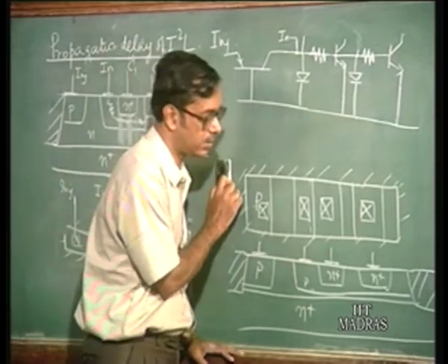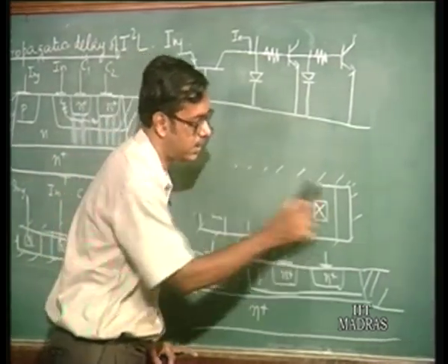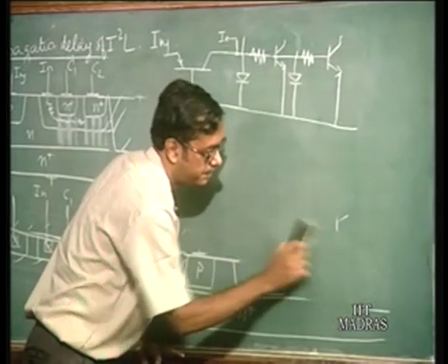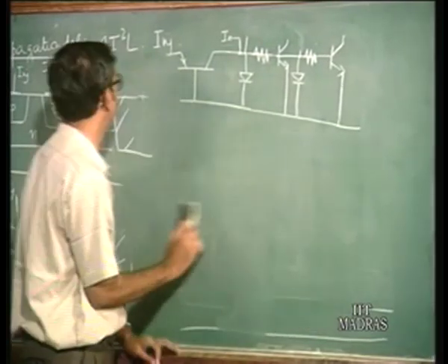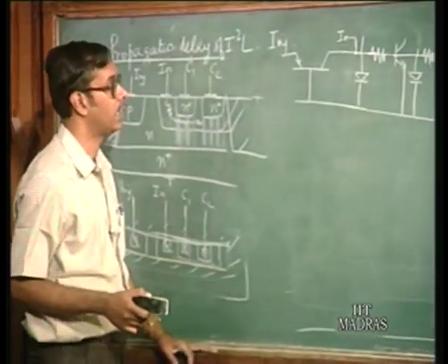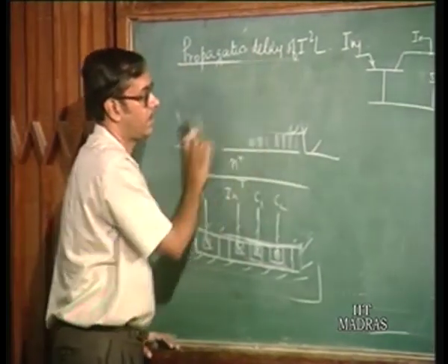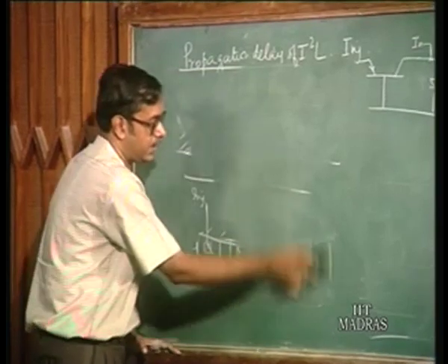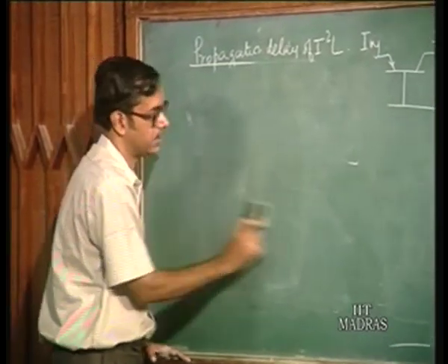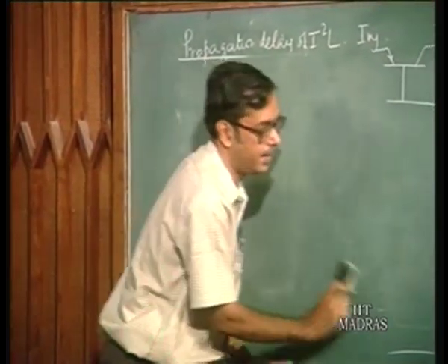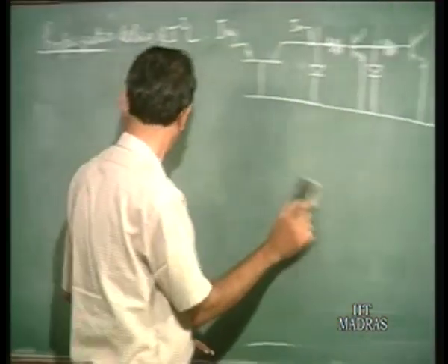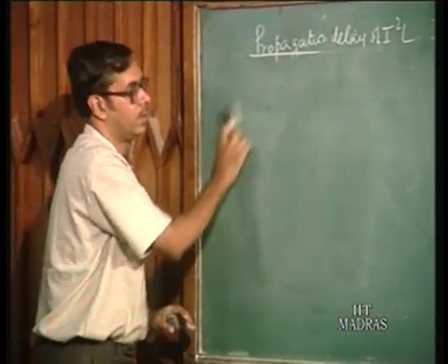So I shall go through the process technology for the self aligned I squared L process, and we shall then understand how it improved the device performance.